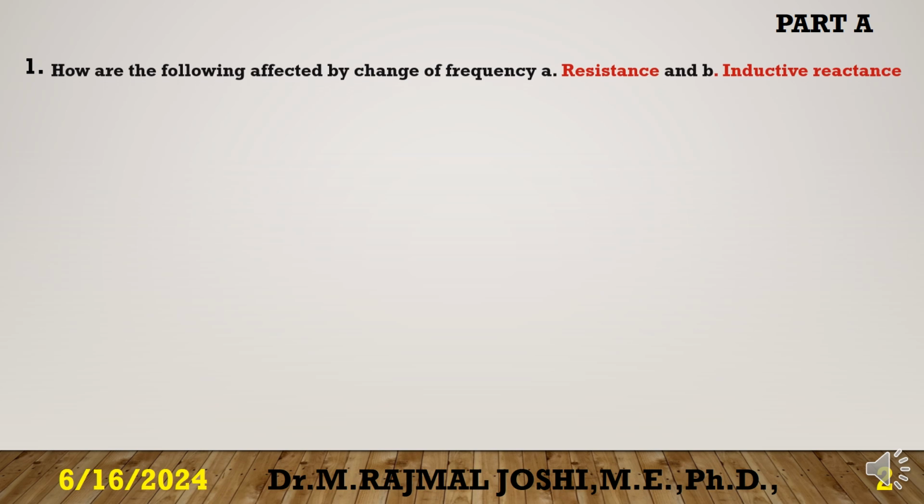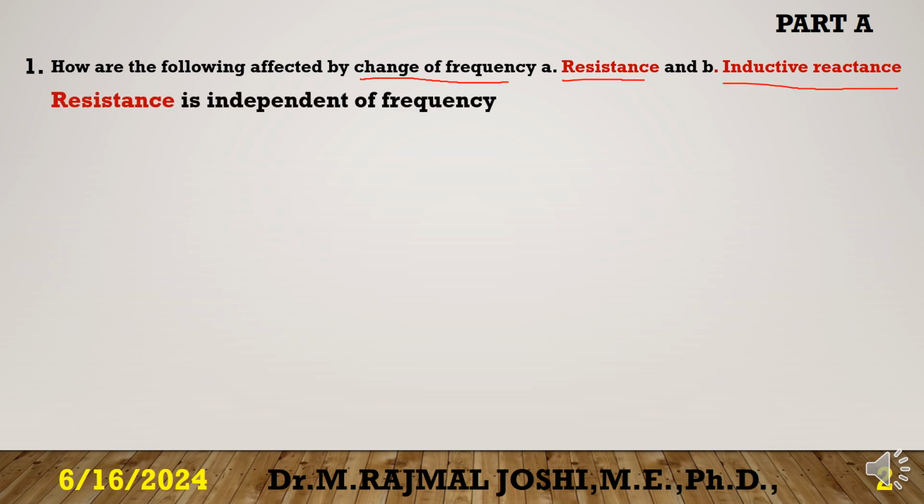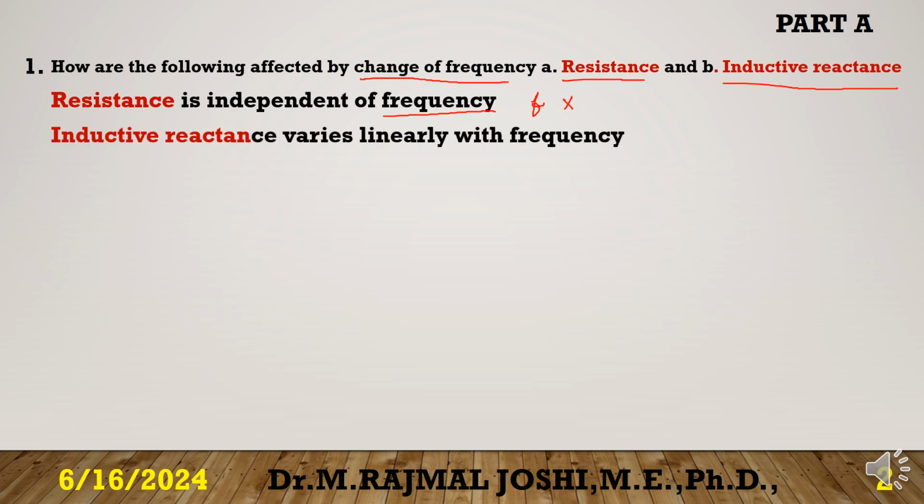How are the following affected by the change of frequency: the resistance and the inductive reactance? Resistance is independent of frequency, which means it does not involve the term frequency. Whereas inductive reactance varies linearly with frequency, where XL is omega L and omega is equal to 2 pi f, where f is the frequency here.